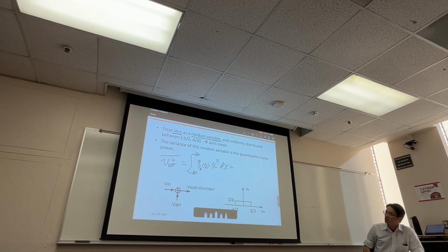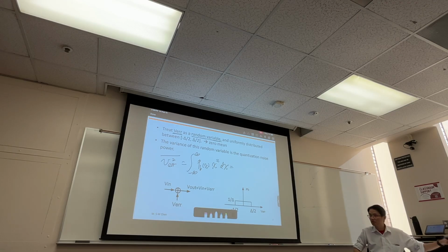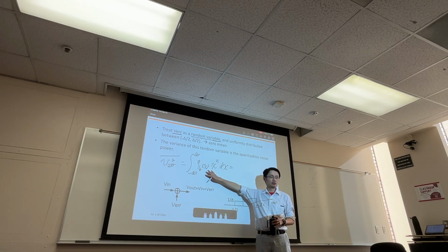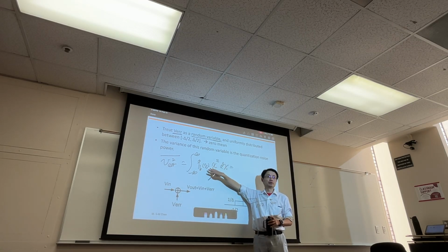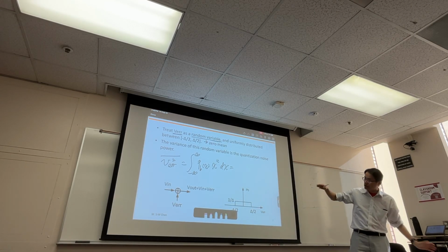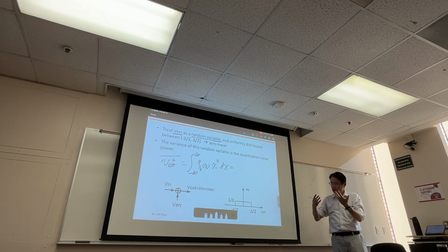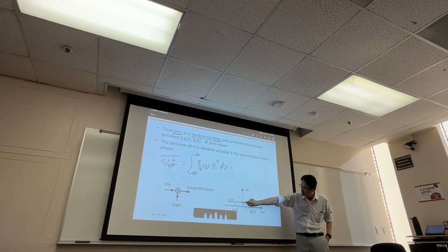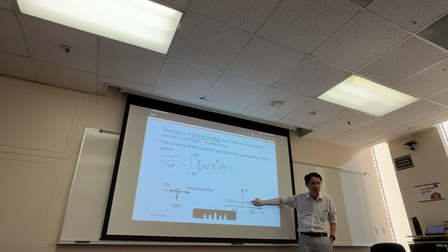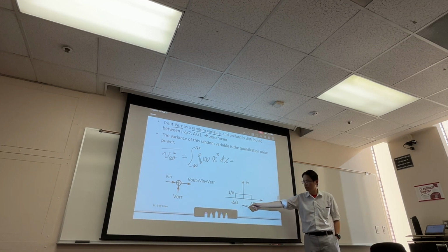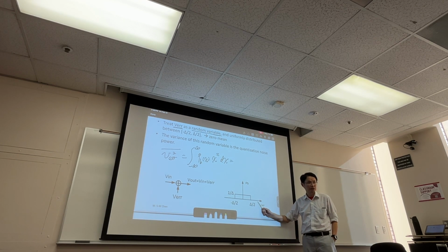So what is the probability density function of my V error, also known as the PDF? Remember PDF, not the Acrobat PDF, but the probability PDF. It's a horizontal line because it's a uniform distribution, between negative delta over 2 and plus delta over 2. So this is the PDF of this.